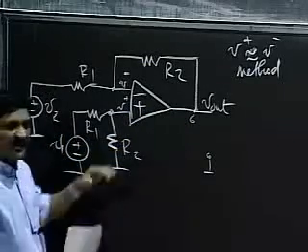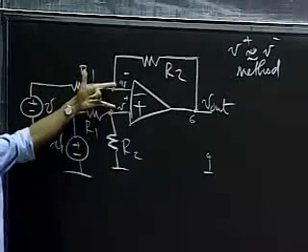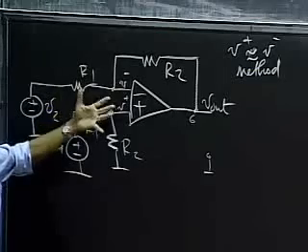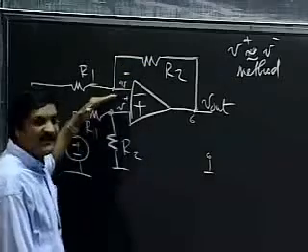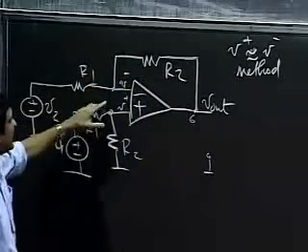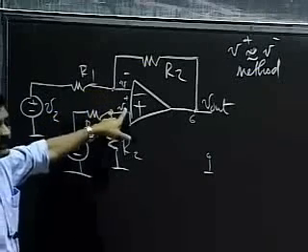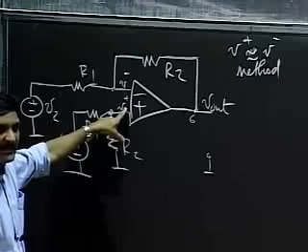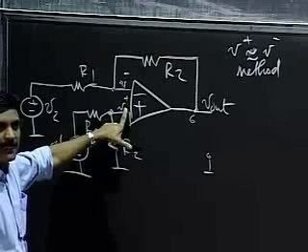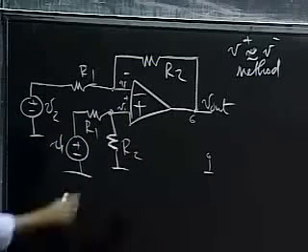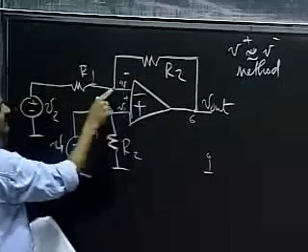So the key thing to observe is that under negative feedback, when the op-amp is not in saturation, the property that V plus equals V minus holds. It's not a magical property. It's simply that when I apply negative feedback, the negative feedback will force this V minus node to be at more or less the same voltage as V plus. Remember, when in doubt, simply go back and think about the anti-lock brakes example we did last time. So if, for example, V plus increases, the output will increase, and so will the voltage here,